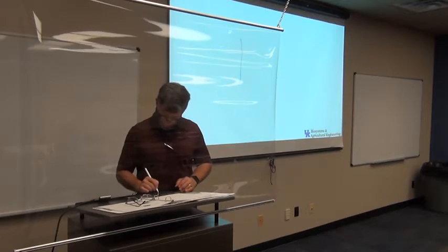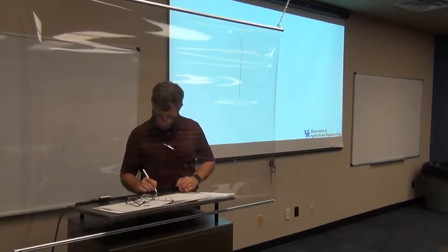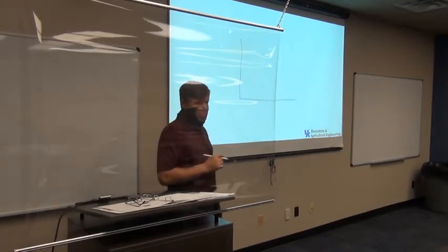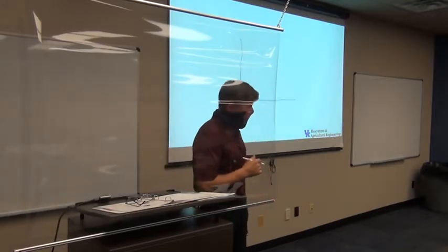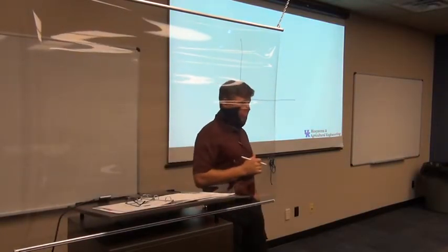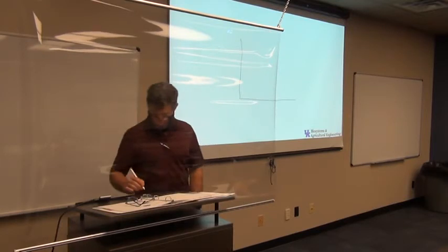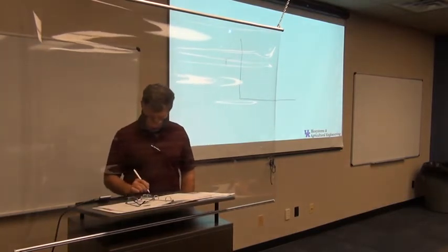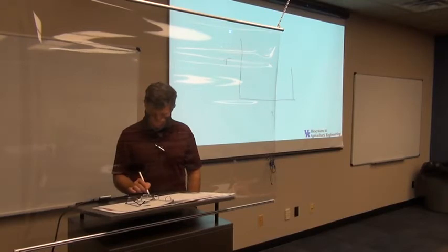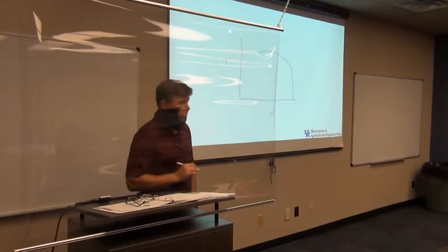So one of the things I asked you to do in the homework, in a couple of those problems, is looking at torque rise or torque reserve. So two different terms used for the same thing, torque rise and torque reserve. If we go back to our torque versus speed curve, it looks something like this. You collect the data in the lab, so we got the governor control zone, governor max here, and then we get a big curve that'll do something like that.